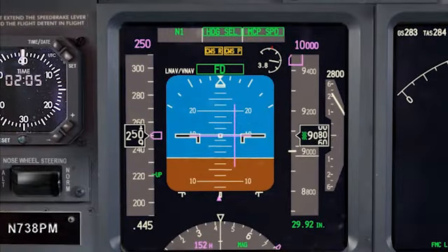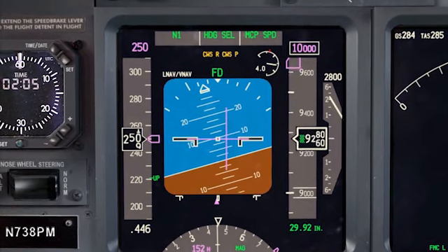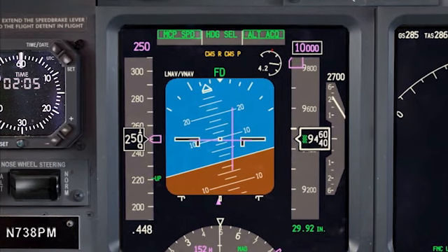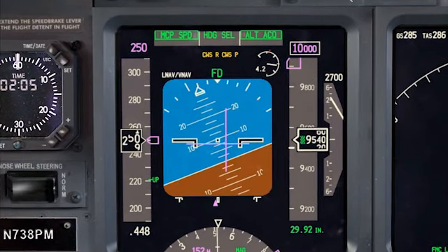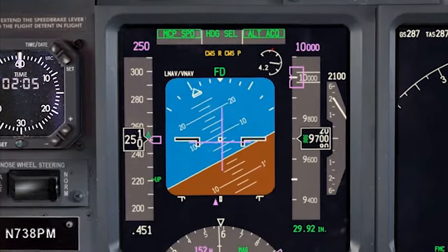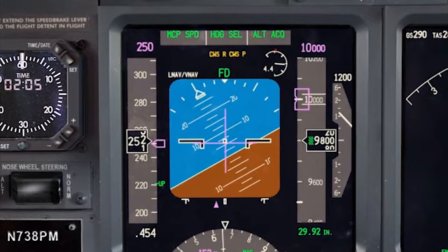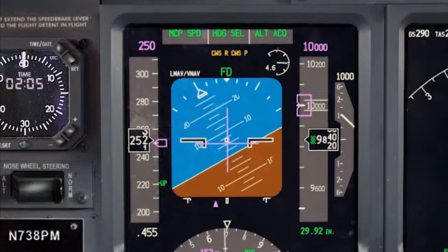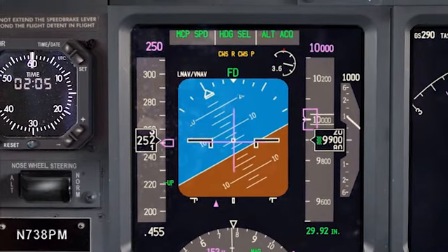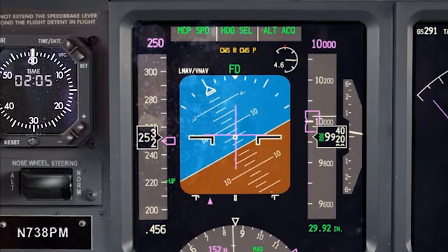For those of you familiar with our MD-11 training, you know that aircraft has a system called the LSAS. Essentially, the pilot doesn't have to trim. The pilot simply places the vertical target where desired, and the system will adjust automatically and keep that pitch attitude. Control wheel steering, although an arguably simplified version of the MD-11 LSAS, can hold pilot-commanded roll and pitch.